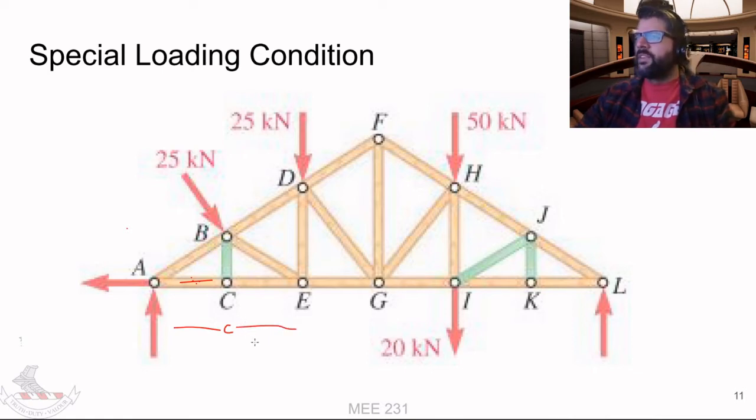So basically, it'll have just enough to keep it in equilibrium like that. But for the purposes of your static analysis, we're assuming that's 0. So that one can go away because of that joint here. So at B, it'll simplify your analysis because then you're only working with the 4 forces: the applied force, and then AB, BD, and BE.